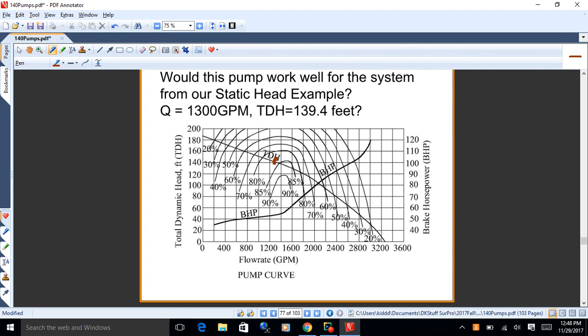Now, if you got a pump that isn't running properly, you can do some things. You can change piping arrangements. You could perhaps lower it a little bit if your NPSH isn't working, if you're getting some cavitation. The other thing you can do for a pump is start replacing impellers, going with a larger or smaller impeller. That's a common way to modify a pump. But there might be cases where what you got just ain't going to do what you want it to do. So at the very beginning when you're designing something like this, you want to design the pump so that it runs efficiently.